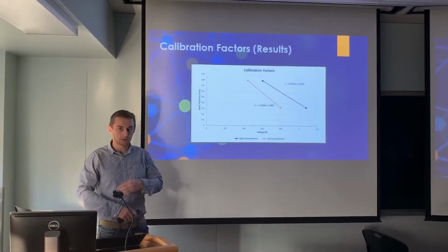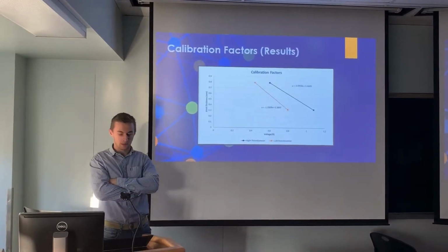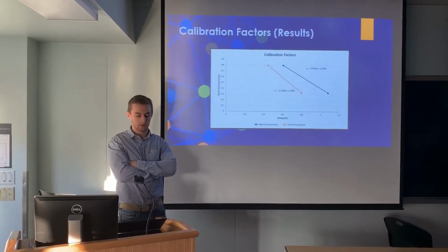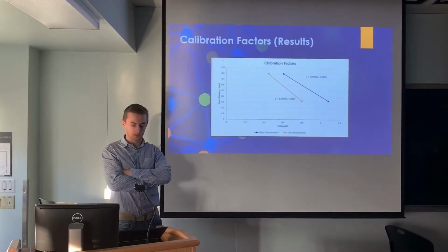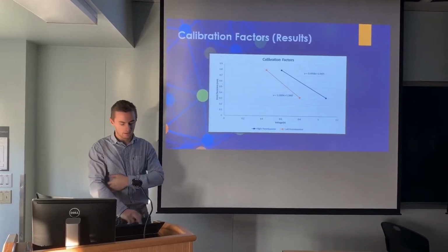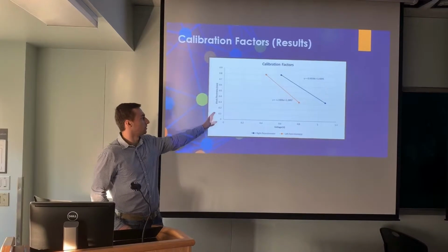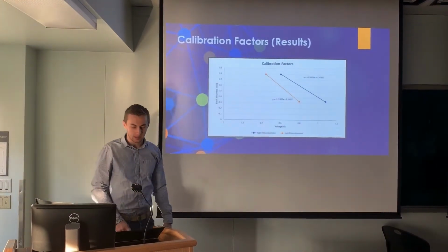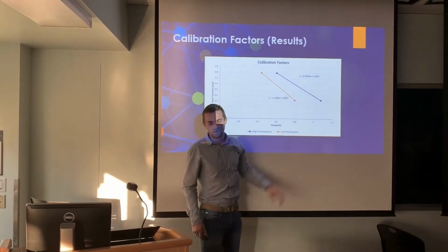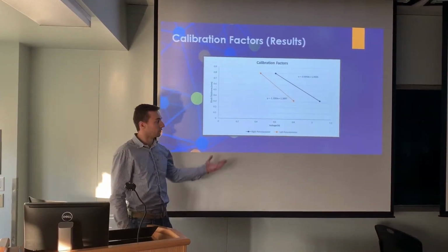The potentiometers measure a voltage, but the measurement we desired was beam deflection. Therefore, both the potentiometers were calibrated at the beginning of the experiment by applying known deflections to the sensor, collecting data for the corresponding voltage. As you can see from the figure on the screen, we've graphed deflection versus voltage and used a trend line between points to find the relation from the equation of the curve.